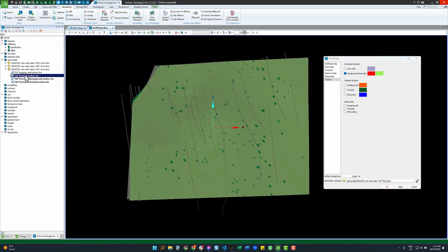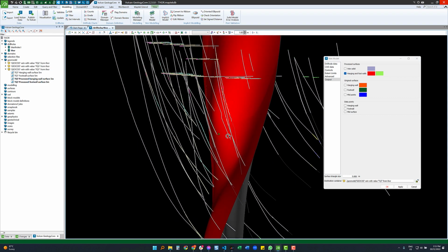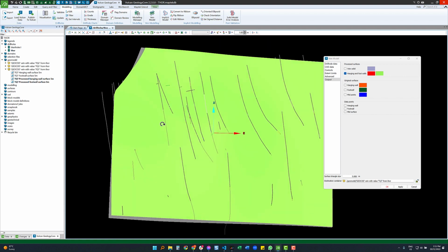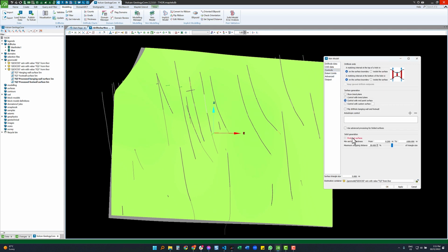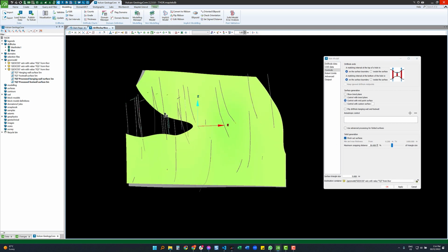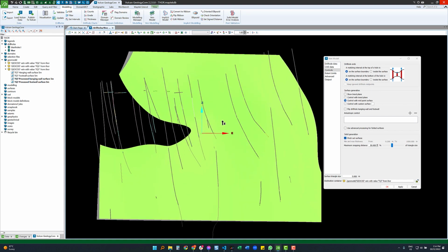and get rid of my two original ones, you can see it's kind of made this section here to maintain that minimum thickness that we asked it to. Right. My other option, if I went into my controls and turned the pinch out option on and rerun it, you see where the two surfaces crossed, it's pinched them out. So it's booleaned out the two shapes. Right, so just two different ways that you can handle those situations.